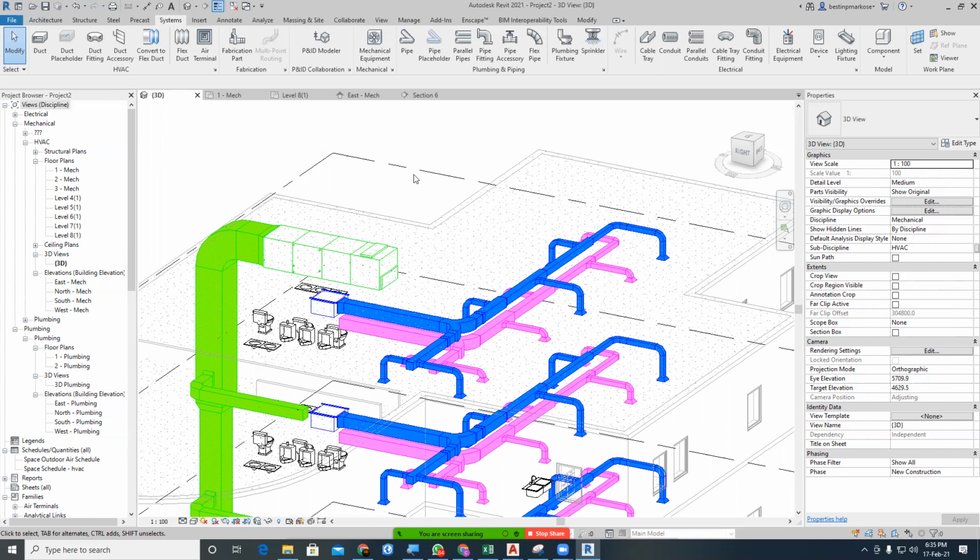So in that, all the rod size and everything we have to give, and the distancing and all. That also we can give as manual input. What distance we have to place, all those distances we have to give. I think that is required in the LOD 500 series. Hangers and supports, everything.